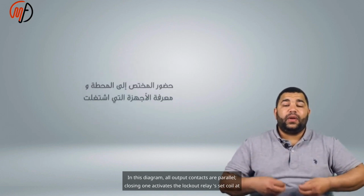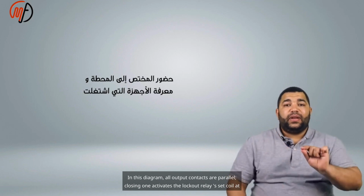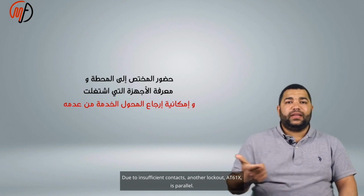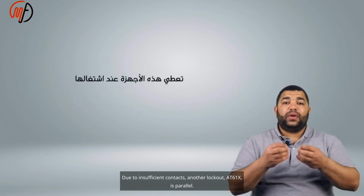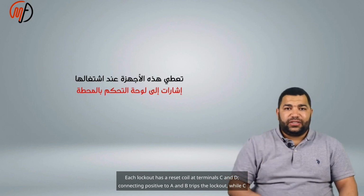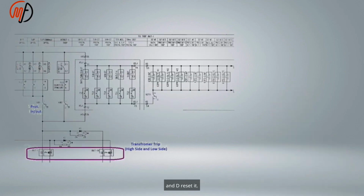In this diagram, all output contacts are in parallel. Closing one activates the lockout relay's set coil at terminals A and B. Due to insufficient contacts, another lockout, 86T1X, is connected in parallel. Each lockout has a reset coil at terminals C and D. Connecting positive to A and B trips the lockout, while C and D reset it.